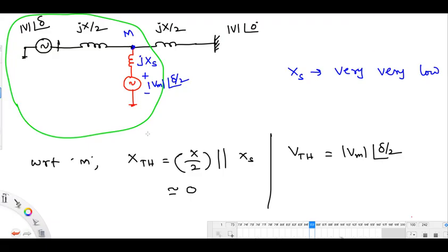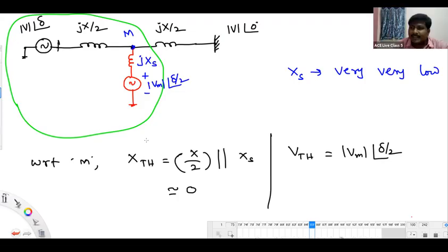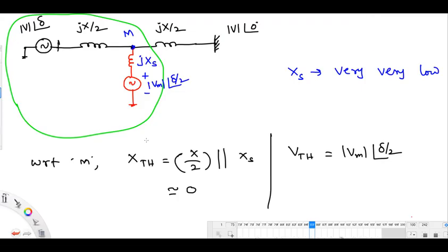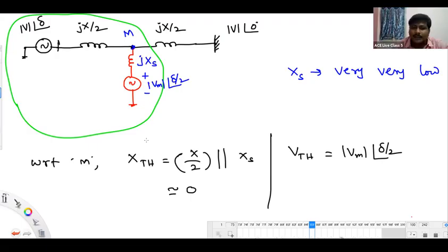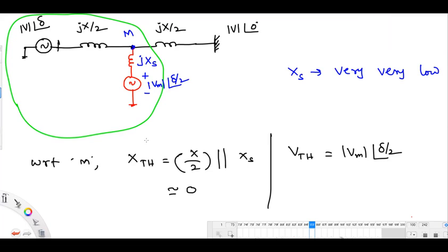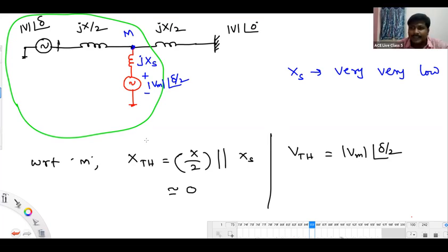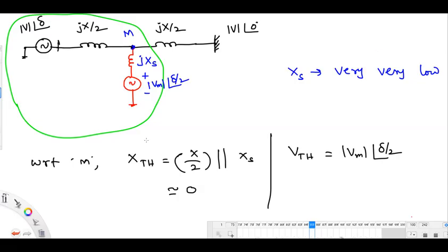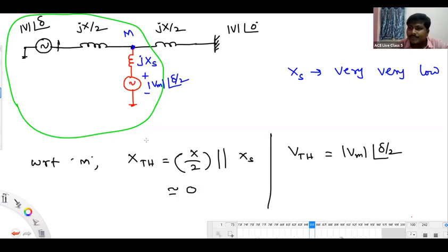Do we have only one single generator or many generators? Many, sir. According to the generator rotor speed, it will induce an EMF at a certain frequency. If the synchronous machines are not rotating at the same speed, definitely the frequency of the induced EMF will be different from one machine to another.